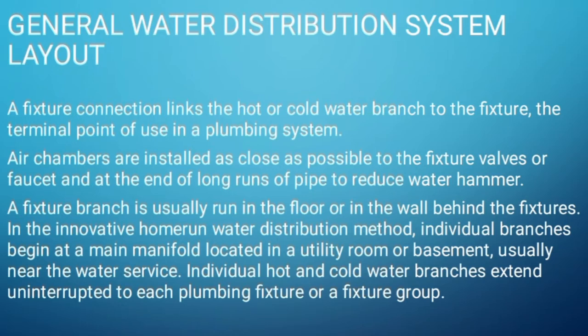A shut-off valve is typically located in the hot and cold water supply at the fixture connection, like what I said a while ago. Air chambers are installed as close as possible to the fixture valves or faucet and at the end of long runs of pipe to reduce water hammer.